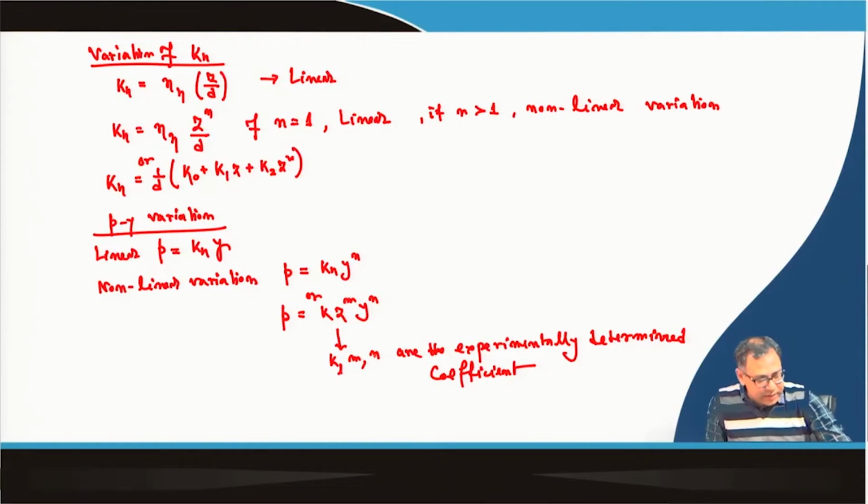So, that means here not only can you give different variation of kh, but you can give different variation of the py. That means, whether you put a linear variation, as in the previous expressions where the stress strain behavior or the load settlement behavior is linear, you can put non-linear variation also.